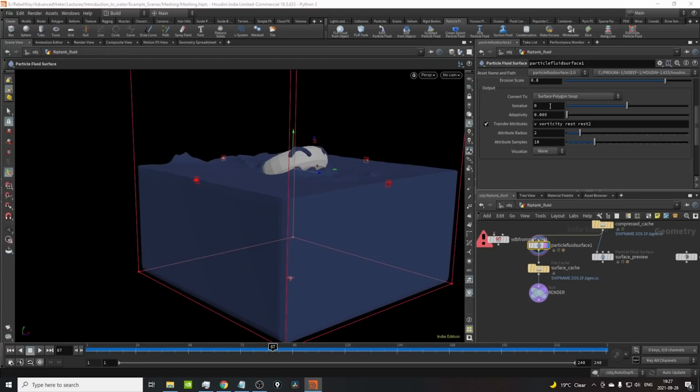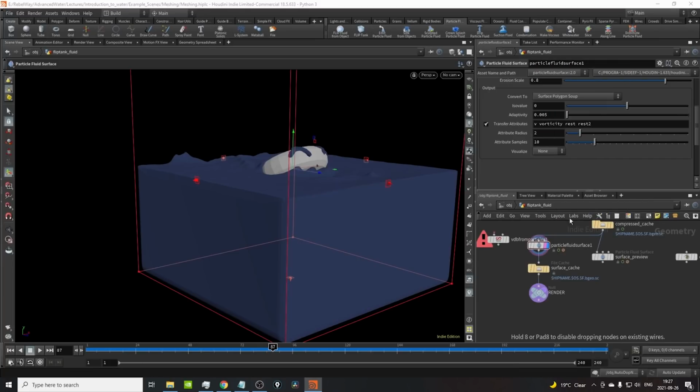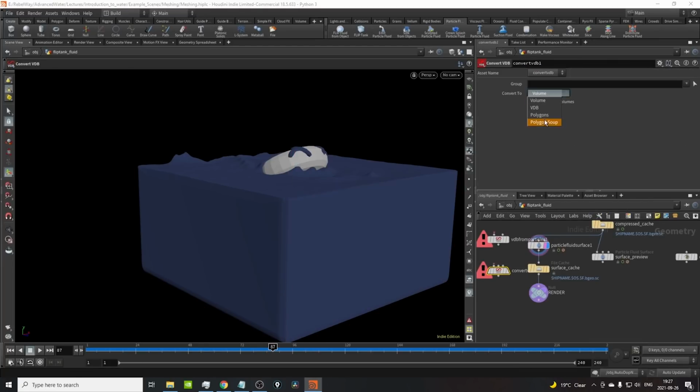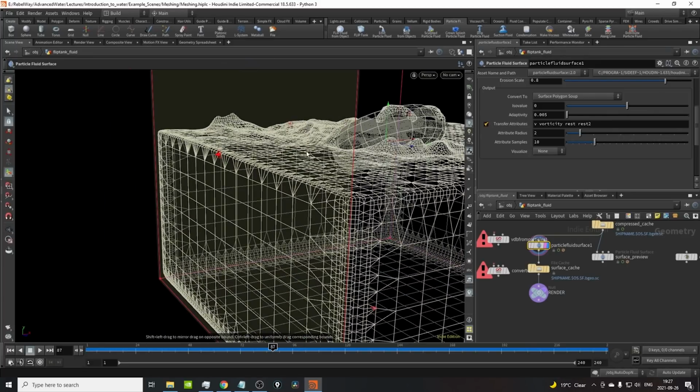And then we have the standard VDB convert option if we go to polygons, which is just, how much of the surface should we eat away, where 0, it's an SDF, so 0 having it as the point of building the mesh is quite nice. And adaptivity simply describes how much resolution exists on flat areas.